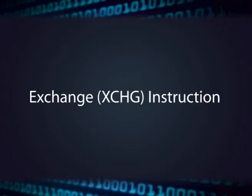The next category after move is the exchange instruction. The short form of exchange is XCHG. In an exchange instruction, the contents of the specified operand pairs are interchanged, and an exchange operation can be performed between a pair of operands using multiple move instructions.